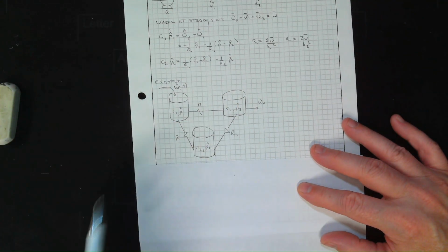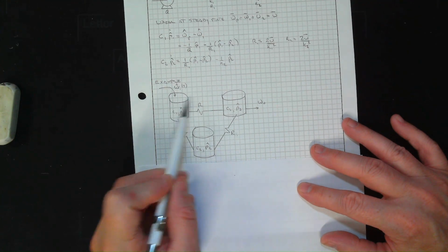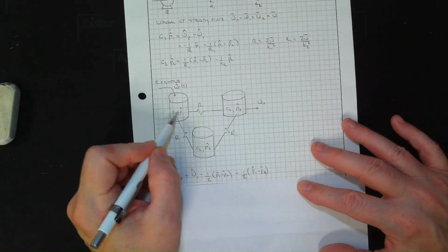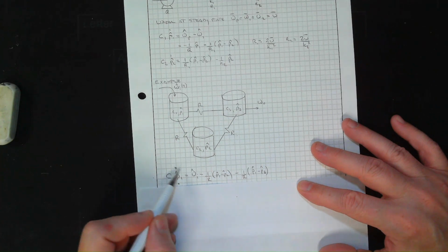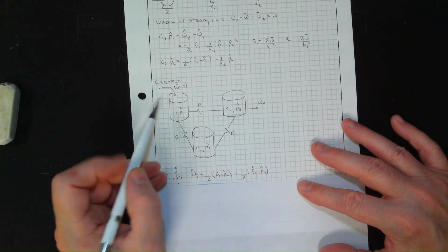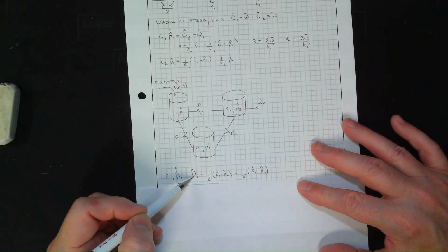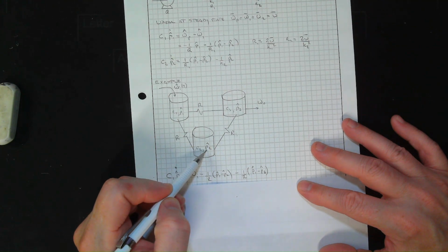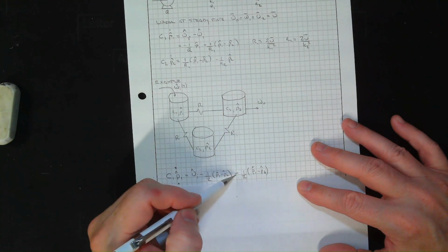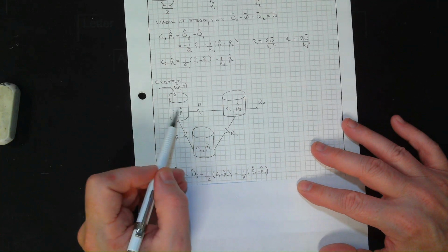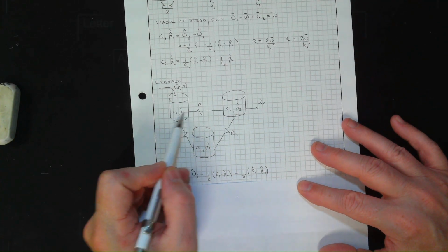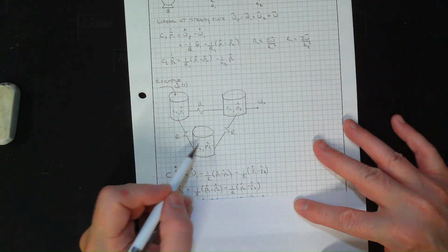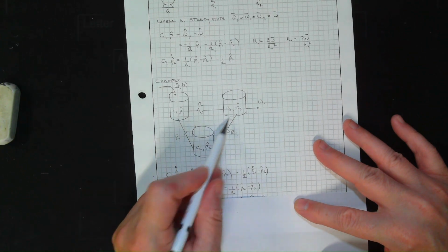Want to model this? Okay. We have an equation for every tank, just like every mass. So we have C1 P1 hat dot, the derivative equals a flow in minus flow out. Well, flow in, we'll take the perturbation flow, minus 1 over R, P1 hat minus P2 hat, and then minus flow leaving, we're assuming it's leaving, 1 over R, P1 minus P3 hats. All done.